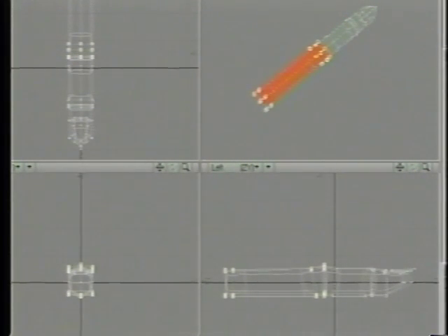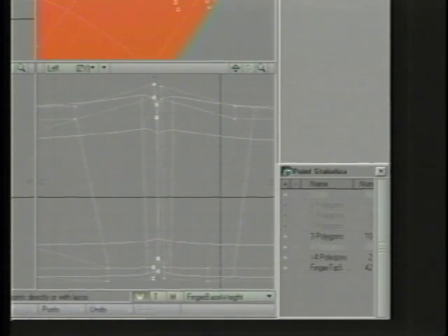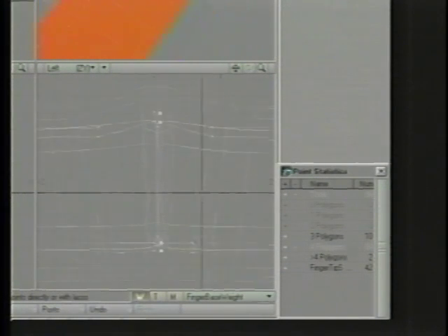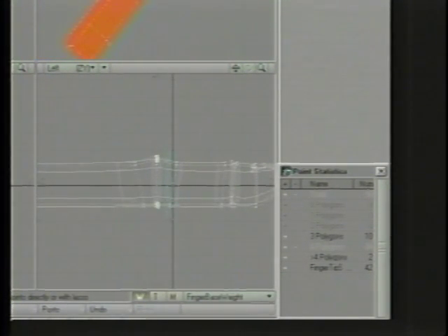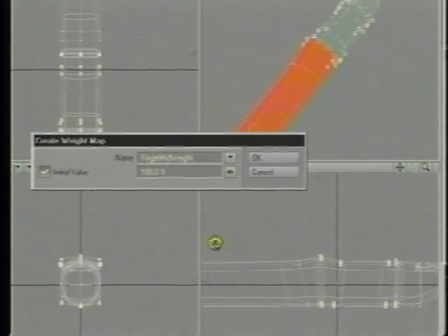Great. So now I've got the base of the finger there. And now I need to do the midsection. So to do the midsection, again, I'm going to zoom in here. I'm going to deselect these and zoom in on those points. I want to make sure I don't get any crossover. So I'm making note of which points here are on the last weight. And now I'll just select these on this side. Then zoom out a little bit. And now I can carelessly select all these points here, knowing that I crossed over into the fingertip. Because I can come over here to my fingertip selection and tell it to subtract anybody that had fingertip selection. Now I know I only have points that were in the midsection because I've deselected any that were also assigned to the tip. And we say new, and this is going to be finger mid weight.